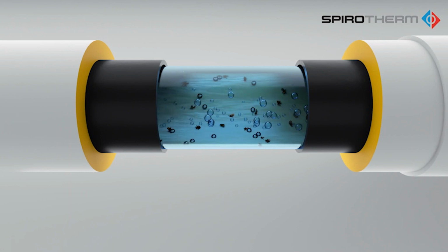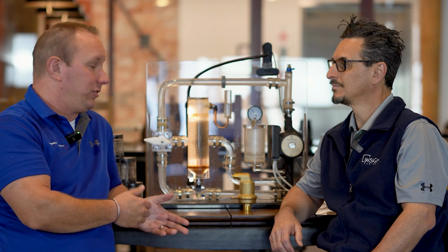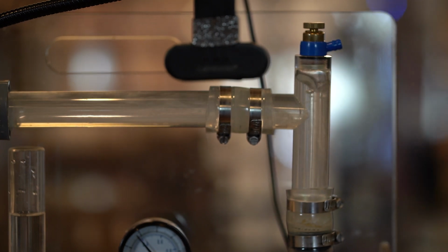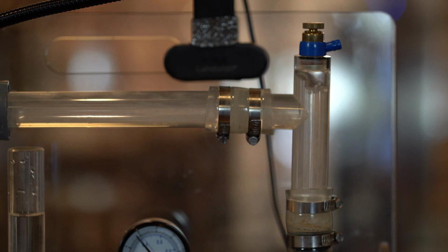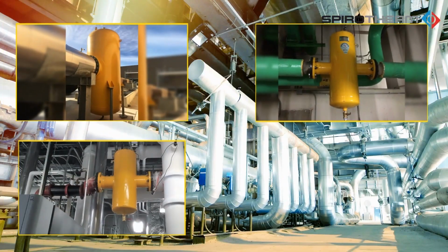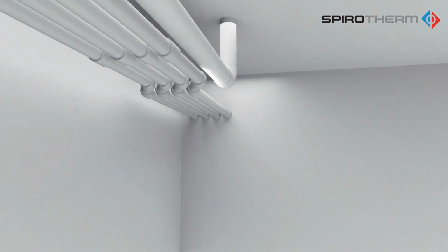Whereas if it's just air in the system, you might just see, for instance, my 700-ton chiller is only giving me 650-ton output, and I don't know why. Is rust bad when it's in the system, right? Between rust, mud, or air, they're all an amazing insulator, and we don't want to insulate the inside of the pipe.